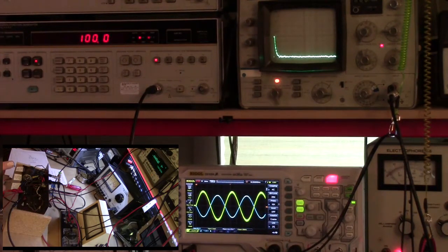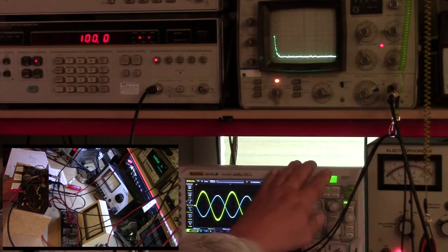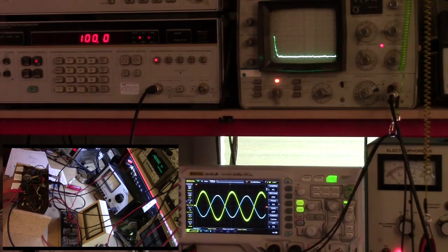Let's look at the microphonics. So what I'm going to do is tap the tube with my fingernail. Okay, oops, we've got to get this back over here while it's running. You're seeing a little bit of a variance in the signal there on the output signal, but it's not much at all, and I'm really thumping it. So we may not have any microphonics issues. We might be able to run this pentode at that high gain level.